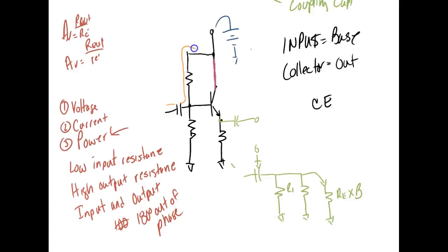It comes in, goes up, slides to this guy here like it's not there, right? Goes to this guy, and we'll always have RE right here. These resistors right here, by the way, are going to be equal. So if this is a 10K, this right here is going to be like a 10K. We'll talk about why later on. Normally, if we're going to operate this Class A.